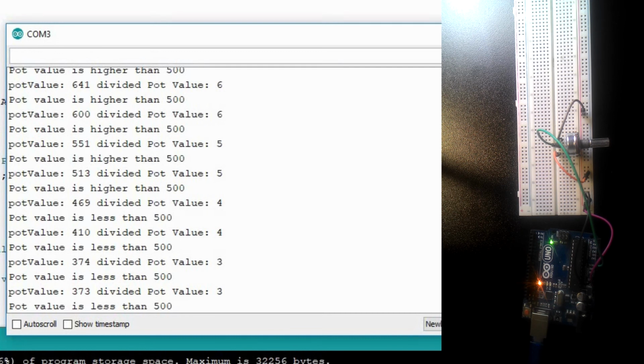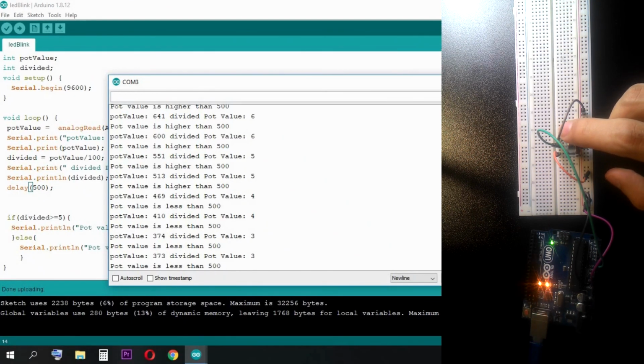I just showed this in the serial monitor, but you can do different stuff. For instance, instead of connecting a potentiometer here, you can connect a battery, and if its charge is below some value, you could say your charge has finished. You can have all kinds of stuff with these analog inputs, because analog inputs are the inputs through which we get data from the outside world. We get the temperature from analog inputs, we get the position of something from analog inputs, servos work with analog inputs, velocity and everything works with these analog inputs, and we take them, we make them digital, and then we write some code and do our operations. So that's all for this lecture.